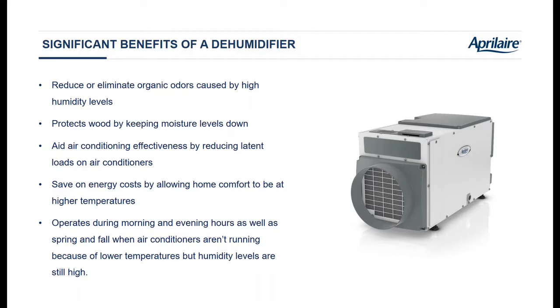Let's talk about why we want to put a dehumidifier into a home. By keeping the relative humidity low, typically below 60% or maybe a little bit drier than that, we can reduce or even eliminate the sort of stinky sneaker smell you get with mildew and mold spores in the space. You've got wood floors, wood cabinetry, musical instruments, even wood-framed windows and doors. If we can control the humidity levels, we can prevent those wood materials from expanding too much.